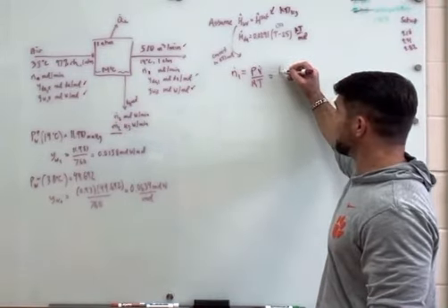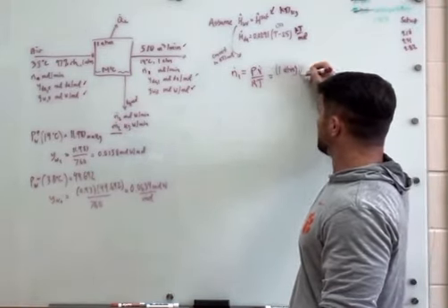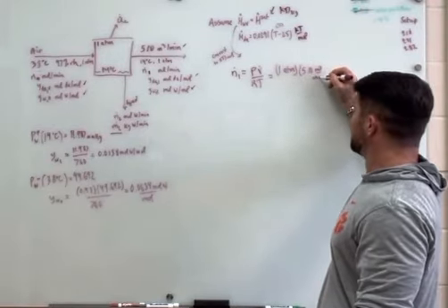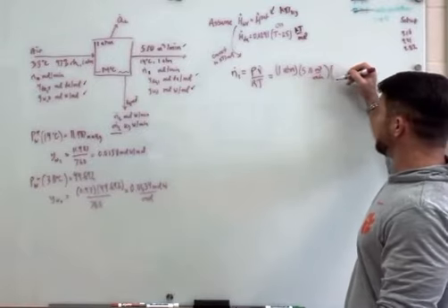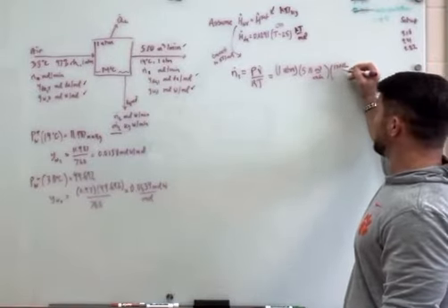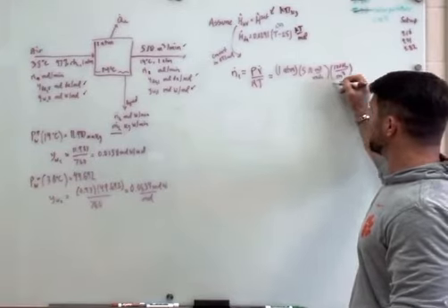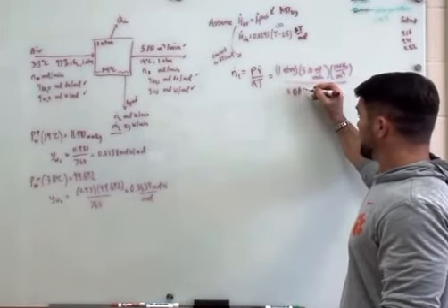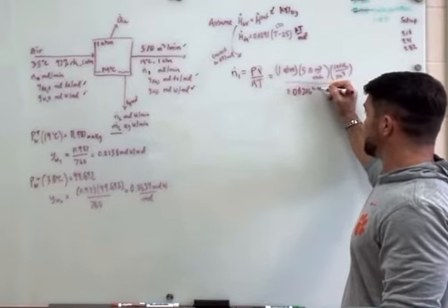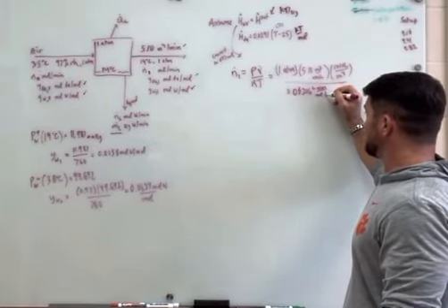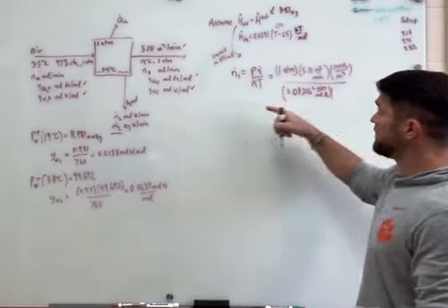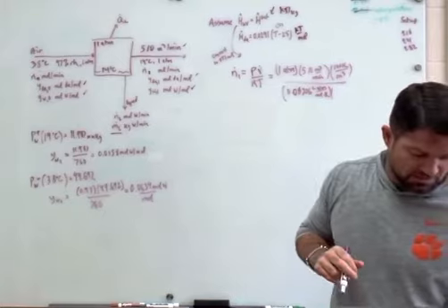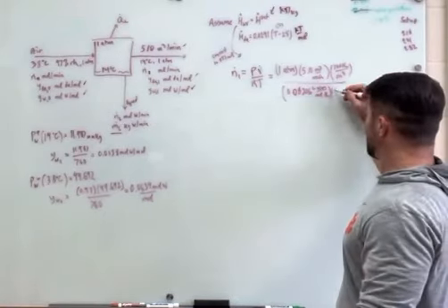The pressure is 1 atmosphere, and the volumetric flow rate given is 510 meters cubed per minute. I'm going to use the R value in terms of liters, so I have 1,000 liters per meter cubed, over 0.08206 liter atm per mole K. The temperature of this stream coming out is 14 degrees C, so that's 287 K.